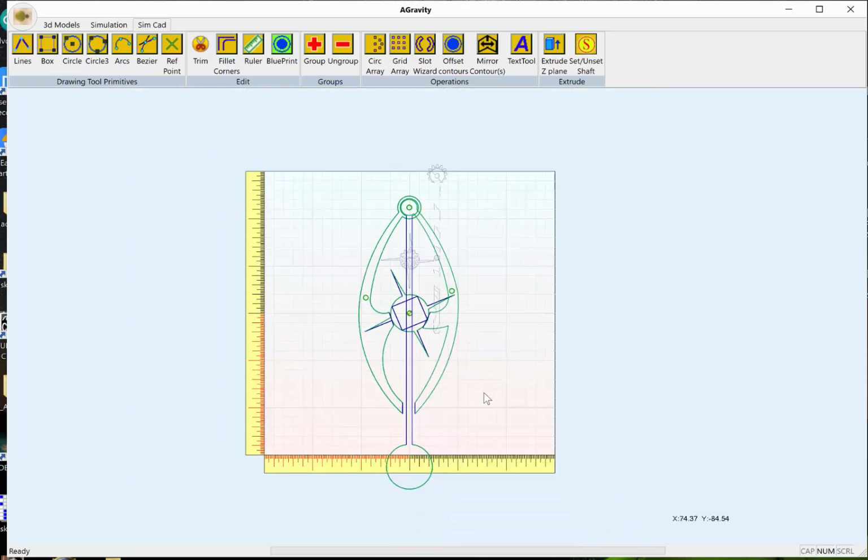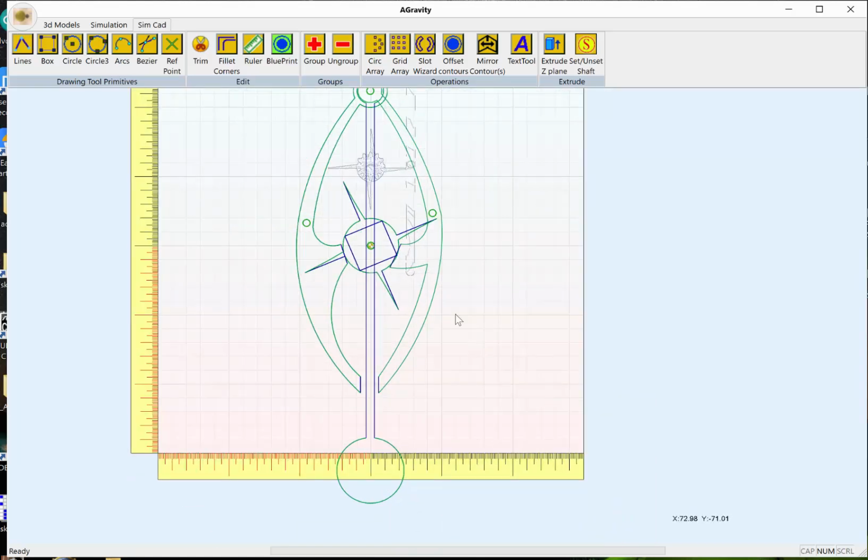The way these gravity escapements work is actually a cocking mechanism. The cam cocks the pallet outwards off of its gravity center and holds it there until the pendulum comes and grabs it, at which time that cocked energy is added to the pendulum, and that's what keeps it swinging.